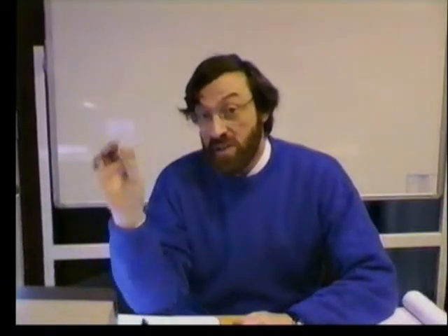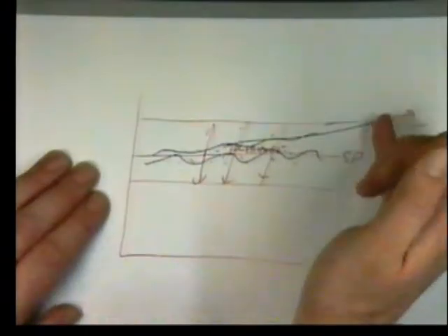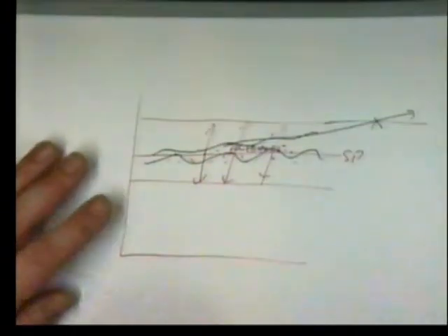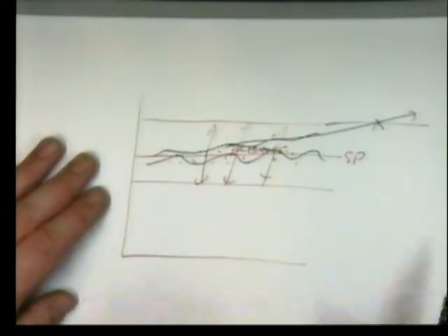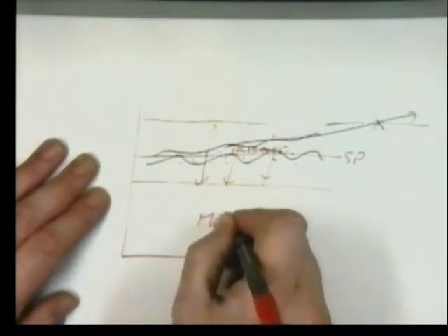It's a statistical concept. Rather than controlling every single minute part of the process, we just let it run. But we sample the product on the output. We don't sample every one. We measure 1 in every few thousand. We draw these trend graphs, and we try and predict something's going to go wrong. And then, well before it goes wrong, we go and correct the process. Now, these are very long timescales. These are months.